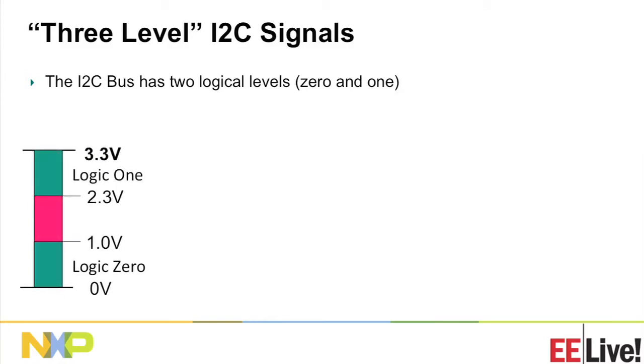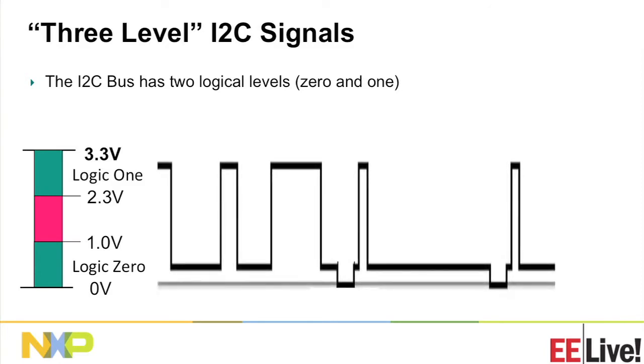you would expect to see a binary signal. But you have this thing that's not quite binary. I see a few people smiling in the audience. You've obviously looked at these signals, and you've noticed that we have 3 levels. It's still a binary signal, so let's just walk through them. The one at the top is obvious. That's logic 1, and that's well in the green zone. The one at the bottom, system ground or very close to it, is obviously logic 0. So what's this odd level halfway up the green bar?